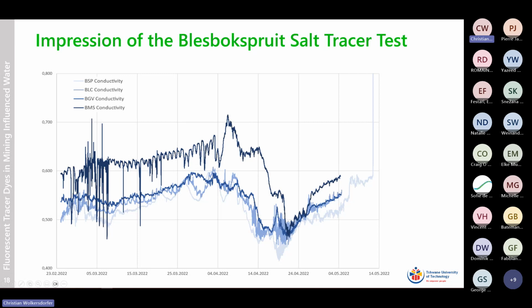You can clearly see before the peak arrives, the electrical conductivity goes down. The reason for that is ion exchange. So calcium and sodium are exchanged. Therefore, the electrical conductivity first goes down and then it goes up again. So that's the peak at the closest injection location.